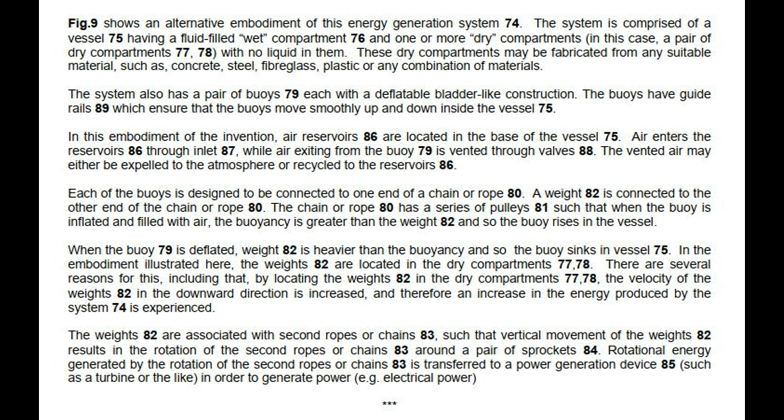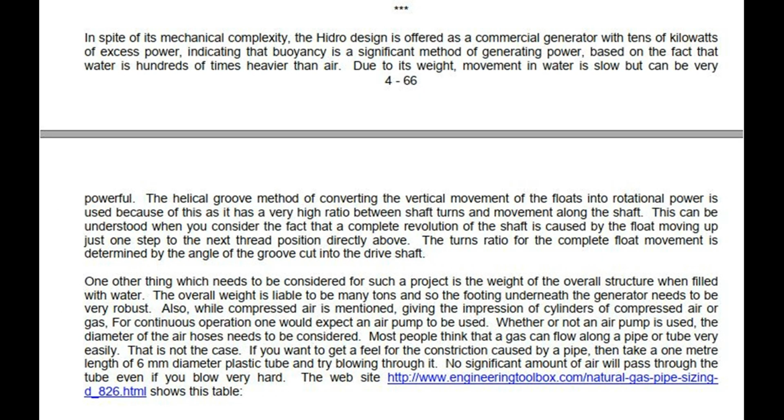In spite of its mechanical complexity, the Hydro design is offered as a commercial generator with tens of kilowatts of excess power, indicating that buoyancy is a significant method of generating power, based on the fact that water is hundreds of times heavier than air. Due to its weight, movement in water is slow but can be very powerful. The helical groove method of converting the vertical movement of the floats into rotational power is used because of this, as it has a very high ratio between shaft turns and movement along the shaft.